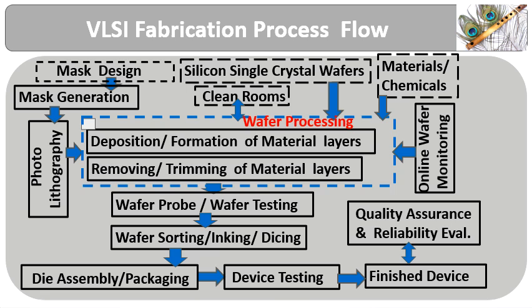Component interconnectivity is established with aluminum or copper interconnects. Chemical and mechanical planarization creates flatness of the created layer surfaces. Tested wafers are then scribed, mounted, bonded and encapsulated to form a finished device. Final electrical testing of the finished device is carried out to ensure conformance to datasheet parameters. Periodically, statistical sampling, batch acceptance for quality assurance, and environmental and reliability tests are carried out to meet different customer commercial, industrial and defense specifications.